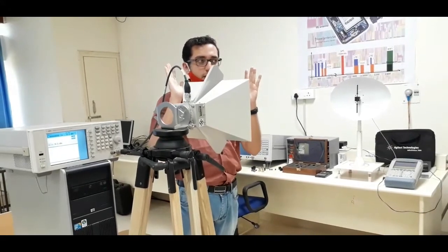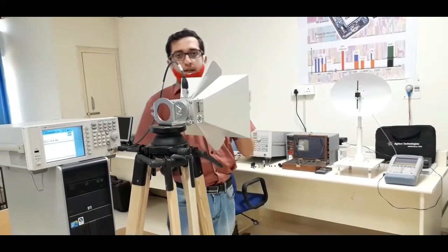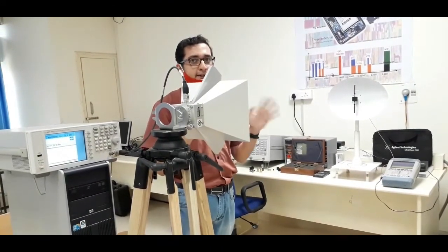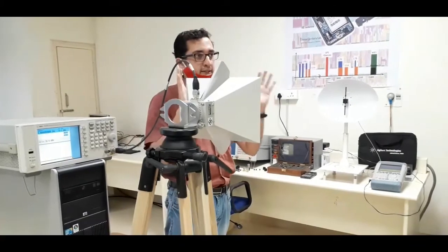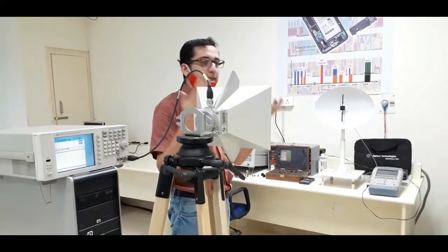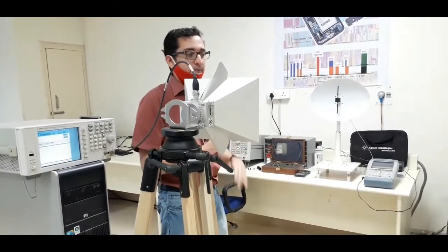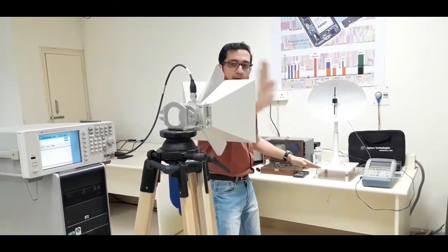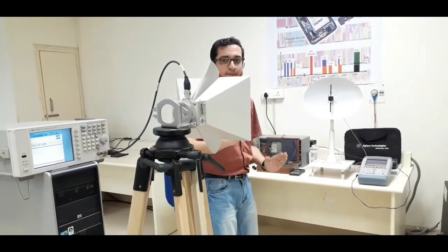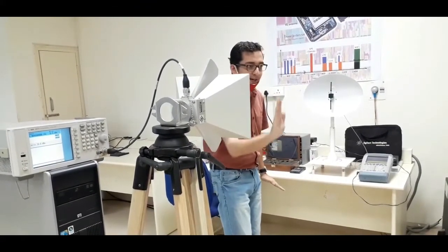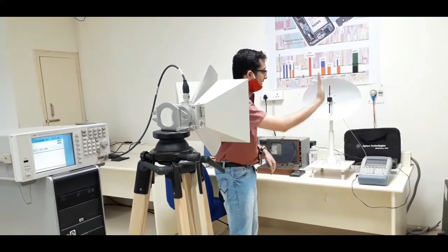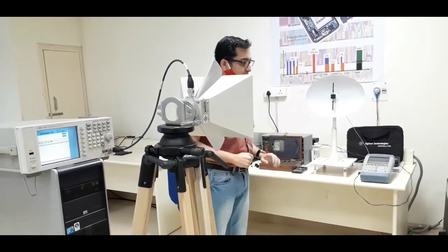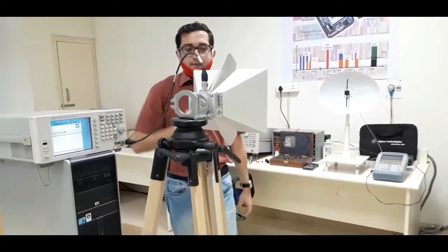Even though these antennas are very different, the common fact about both of them is that they can transmit and receive linearly polarized signals. To be specific, these two can receive vertically polarized signals. What that means is, if this is the transmitting antenna and a wave is traveling from the transmitter antenna to the receiving antenna, then its electric field vector would be aligned vertically, just the way the receiving antenna is oriented. Now let us look at the transmitter